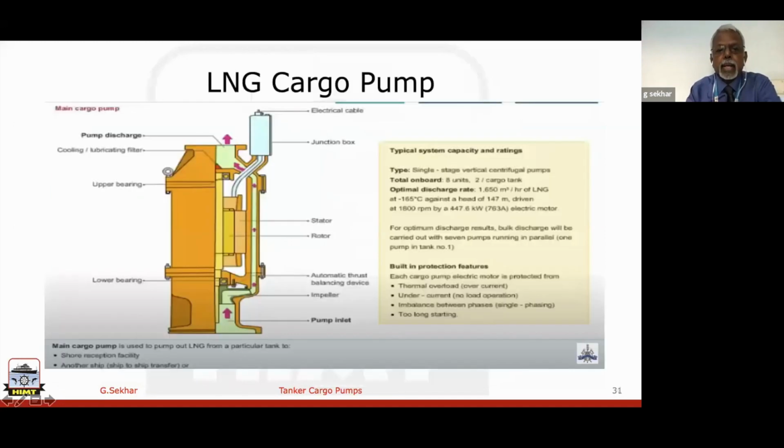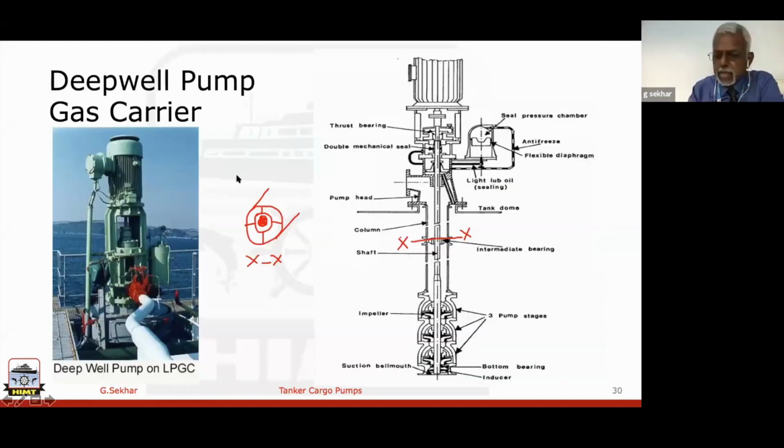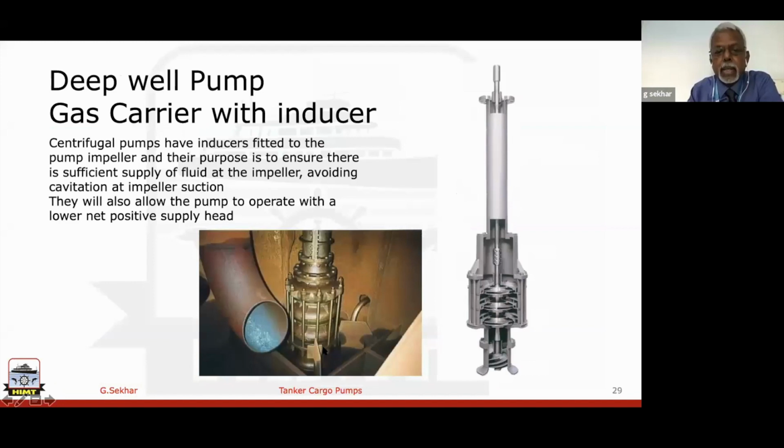And on some LNG ships you may see a cargo pump like this, and very often they also call it a spray pump or stripping pump. Here the arrangement is slightly different, because in the earlier type we saw the motor right on top and the pump elements at the bottom of the tank. Now this is your 3-stage pump. Whereas in this arrangement,